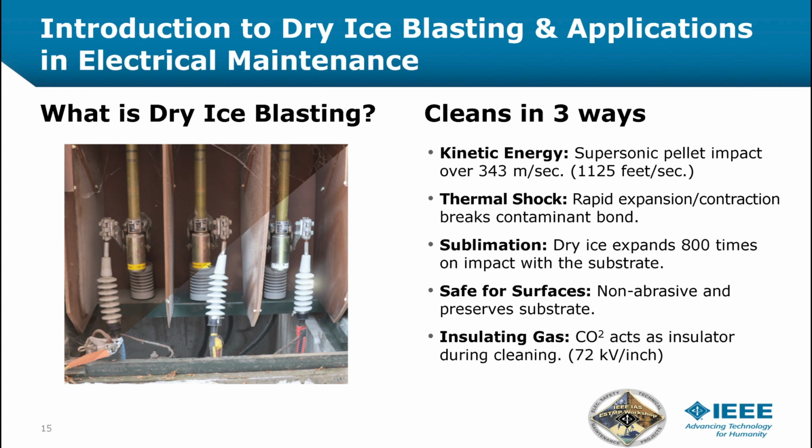Kinetic energy. We accelerate the 3mm pellet, which is basically the size of rice, to above 343 meters per second, or 1,100 feet per second. It's above the speed of sound. It thermally shocks the material that separates the two materials, the contaminant from the host, by rapid expansion, and it cools the contaminant on top.